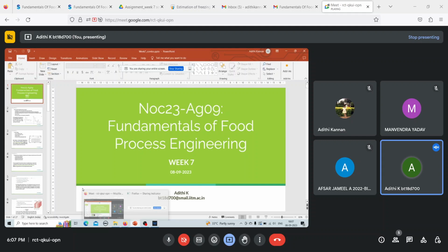So we have all the parameters required given in the question. At the initial condition, freezing time is 200 minutes. The freezing temperature is given as minus 1 degree Celsius. Initially, the air condition is at minus 35 degrees Celsius. And when you change it to minus 25 degrees Celsius, that becomes your TA2. So you have minus 1 minus minus 35 divided by minus 1 minus minus 25, which is TF2 equal to 34 by 24 into 200 minutes. So TF2 is now equal to 283.33 minutes.